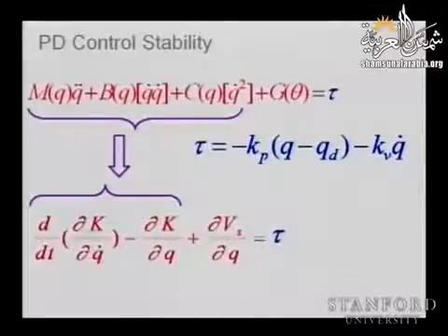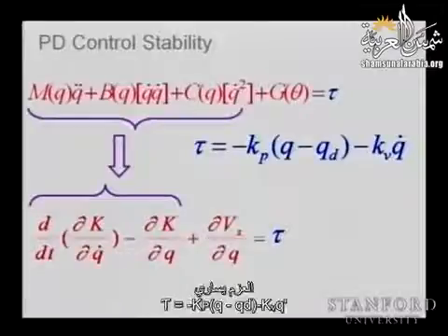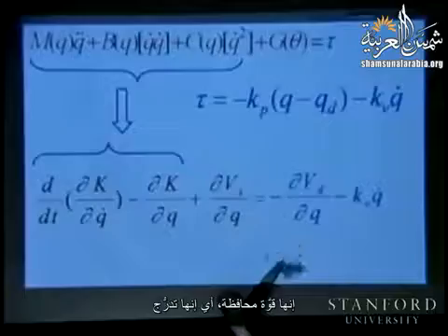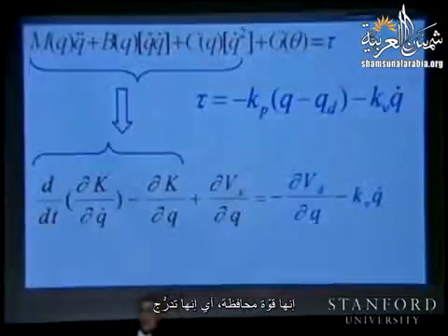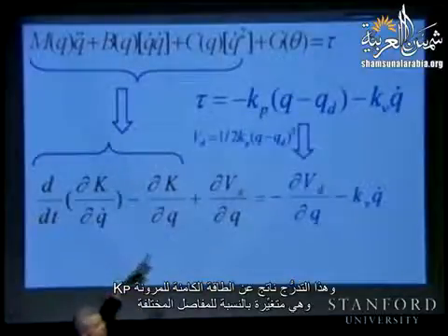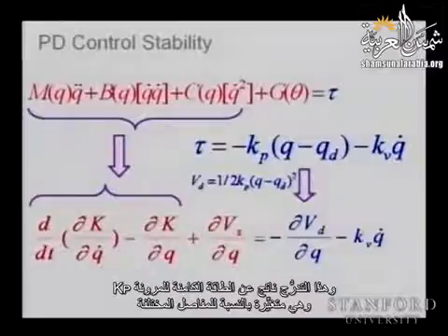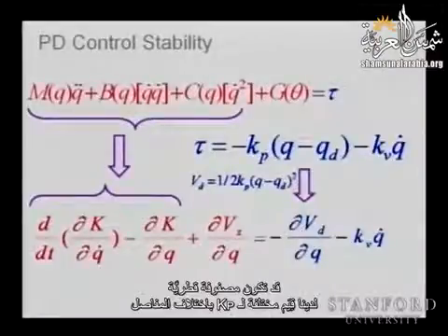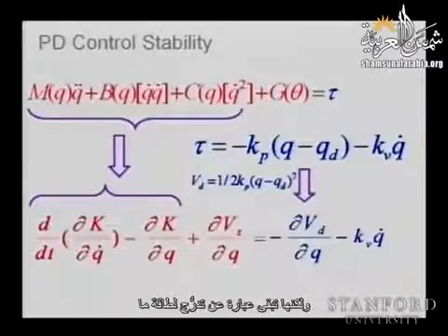So when we apply the torque equal to minus Kp (q minus q desired), essentially we are putting in a first term, this proportional term, which is a gradient, right? It's a conservative force. And this gradient is coming from the potential energy of the springiness Kp, which is varying on different joints. Kp is a diagonal matrix, you can imagine you have different Kps for different joints. But still, it's a gradient of some energy.